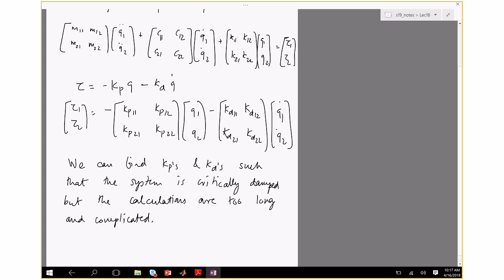And then once I reduce it from 4 numbers to 2 numbers, and 4 numbers to 2 numbers, we'll be designing the first system separately from the second system. So it's like thinking of breaking down a 2 degree of freedom system as two separate 1 degree of freedom systems. And once you do that breaking down, it's like designing two separate controllers using the formulas for a 1 degree of freedom system I talked about. So this is going to make our life much easier.